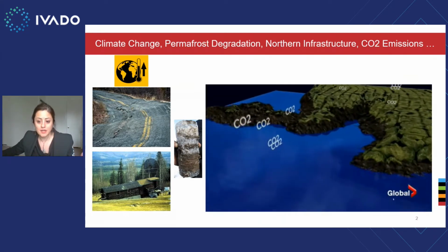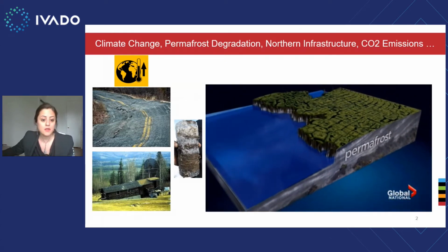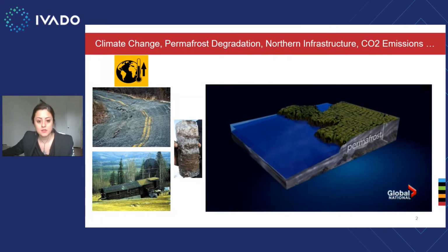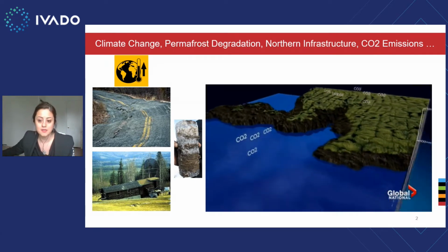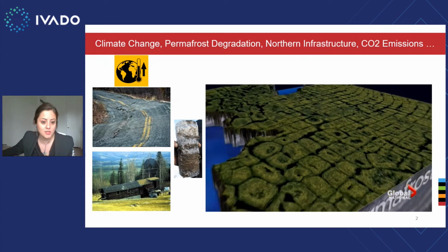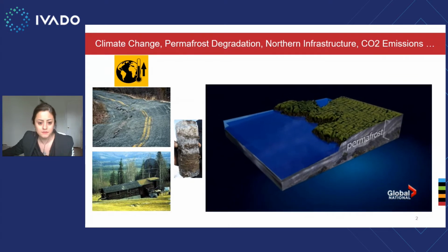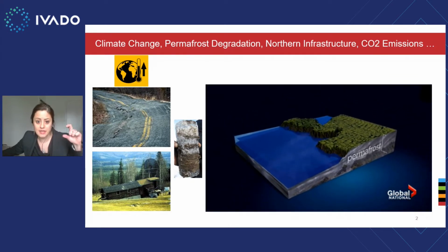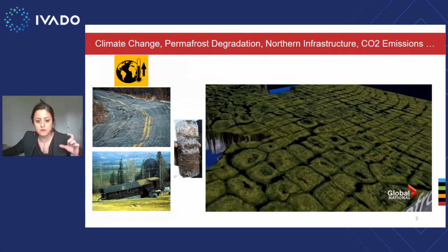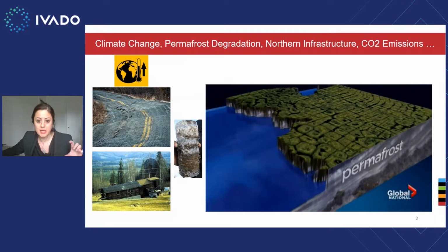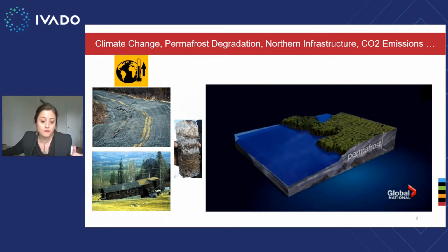Then the shallower layer of the ground in permafrost areas, we call it the active layer, which undergoes seasonal freeze-thaw cycles. The thickness of the active layer depends on local geological and climate conditions, such as vegetation, soil composition, air temperature, solar radiation, wind speed, and so on. Beneath the active layer, we have frozen ground that we call permafrost. And beneath permafrost and these thick, icy layers, we have again unfrozen ground.